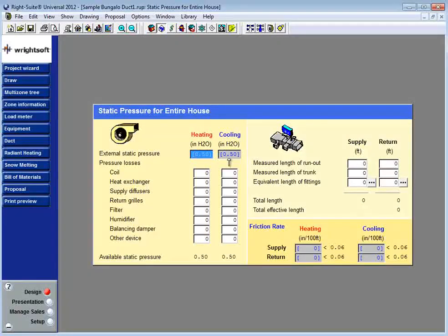With this information on this page, we can now isolate the amount of resistance to be used for our duct design. You see, ductwork won't be the only thing resisting airflow, and since we're designing the duct system to achieve a certain amount of total resistance on the fan, we need to remove those things which are going to add to that resistance that aren't ductwork.